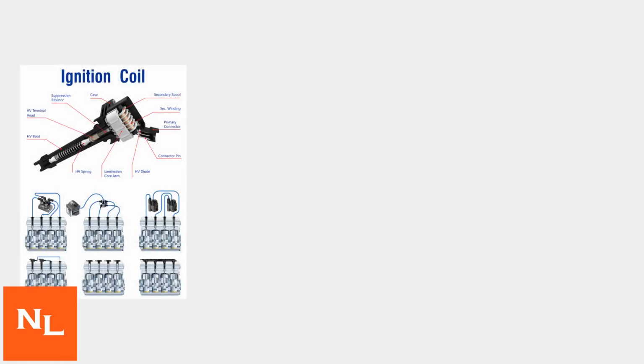When spark plugs aren't the issue, the ignition coil is often the culprit for a cylinder 8 misfire. Ignition coils convert low voltage to high voltage for spark generation. Coils can fail due to heat stress, especially in V8 engines where cylinder 8 is rear-mounted and exposed to higher temperatures. Ignition coils degrade over time, particularly in high-mileage vehicles. Replacing a faulty coil for cylinder 8 costs around $100 to $300, more than spark plugs but still a common repair.